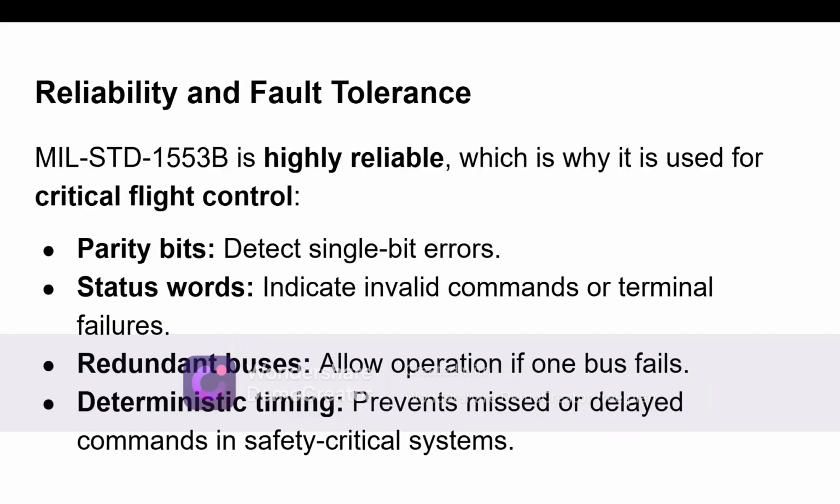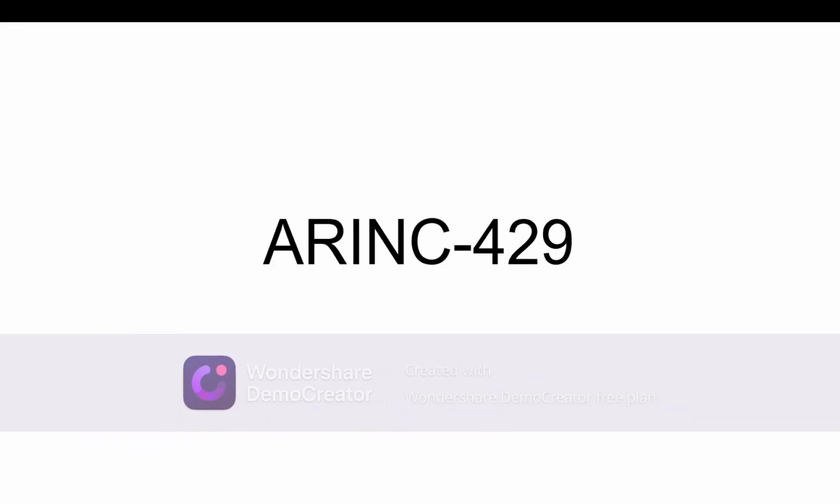Reliability and fault tolerance. MIL-STD-1553B is highly reliable, which is why it is used for critical flight control. Parity bits detect single-bit errors. Status words indicate invalid commands or terminal failures. Redundant buses allow operation if one bus fails. Deterministic timing prevents missed or delayed commands in safety-critical systems.